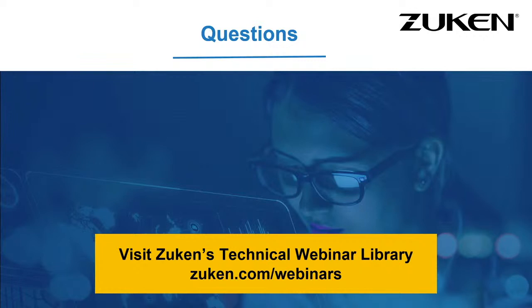Great, thank you. Here's another from Eric, and he's asking, how do I verify that the form board drawing matches the schematic page that I started with? Will the form board drawing created from the transformer tool be parametric with the schematic page? That's a good question. The answer is yes. When you take that schematic data and run through the process of E3 3D routing bridge, getting that data into MCAD and routing it, and then bringing the model into E3 3D Transformer, and ultimately going to the form board, that data should match exactly what you have in your schematics.